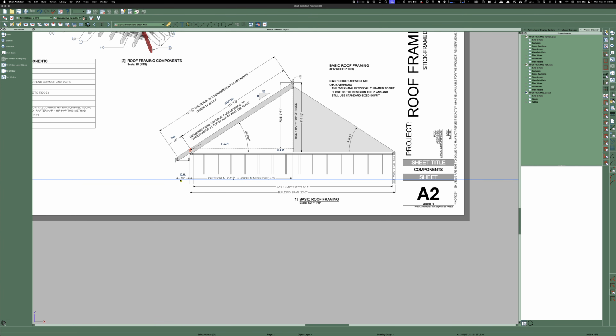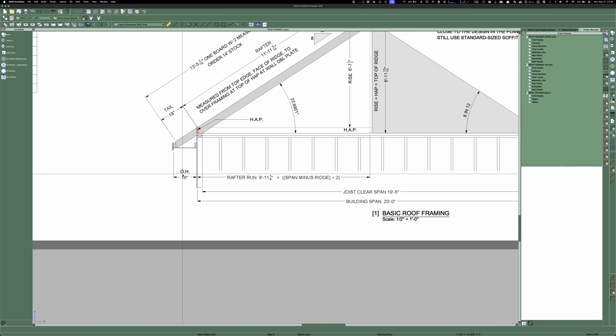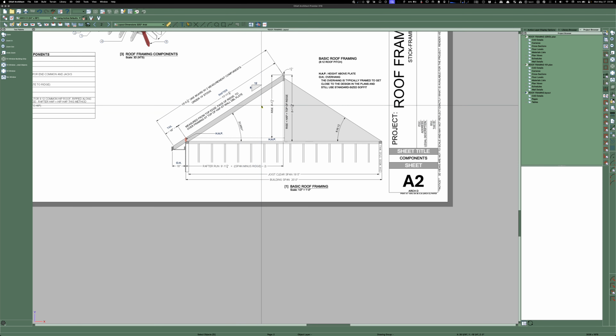And that right there, nobody really gets that picky about it. I just thought back to all the times I've cut roof, and I never really thought about the overhang. I would look at the plans, figure out what it needed to be, cut a tail pattern, and then set the tail pattern down and start measuring rafters, and then grab the tail pattern and trace out the tail, and go to town.